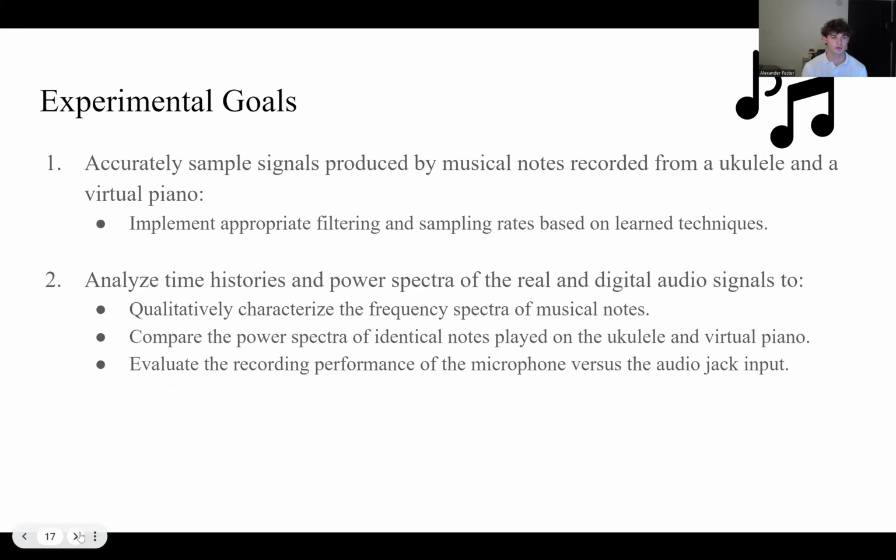In summary, my experimental goals were to sample signals produced by musical notes recorded from both a ukulele and virtual piano using appropriate techniques. Then, I wanted to analyze the time histories and power spectra of the real and digital audio signals to qualitatively characterize the musical notes, to compare the power spectra of identical notes played on different instruments, and to evaluate the recording performance of both the microphone and the audio jack breakout.